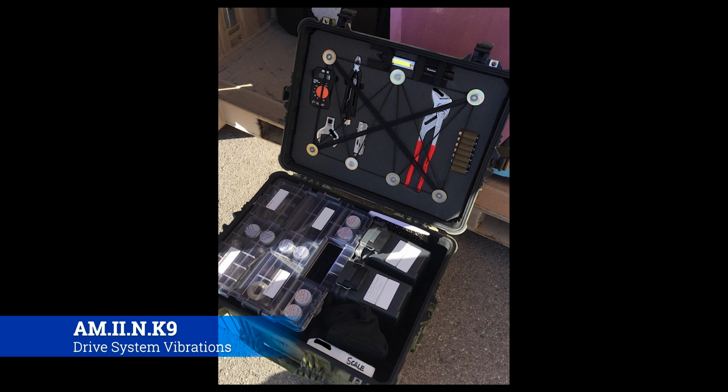Now there are little nuances. So let's say that 500 gram blade, because it's an older blade, is eroded on the tip, particularly a lot, and maybe some other little things have happened to it. Maybe it got dinged or chipped somewhere on the blade. And so even though the tag says it's 500 grams, it's actually only like 490 grams.